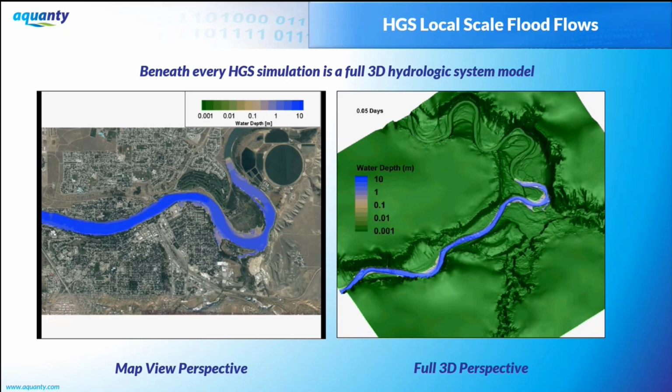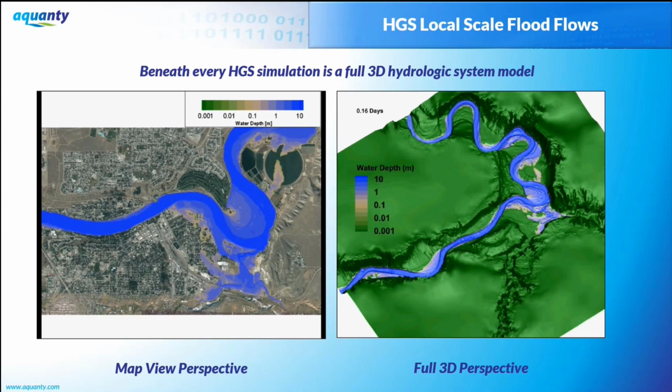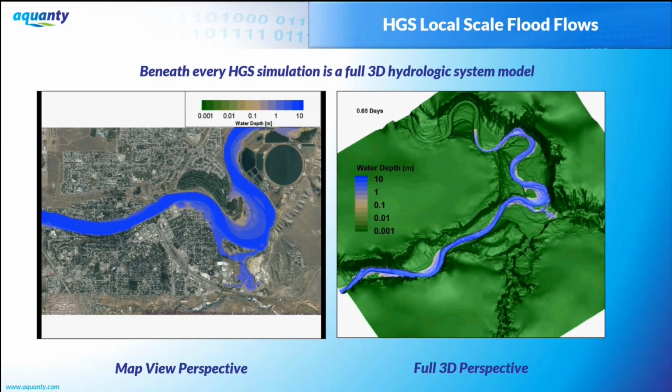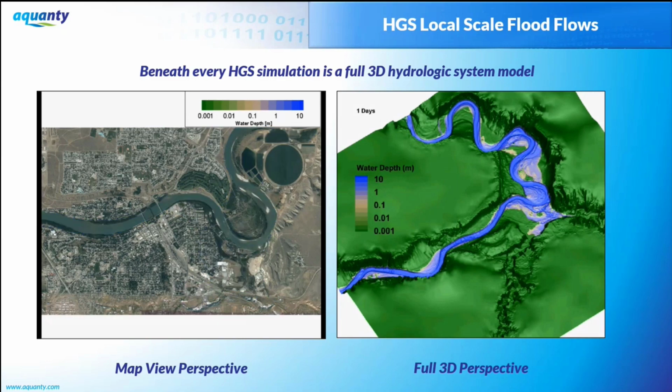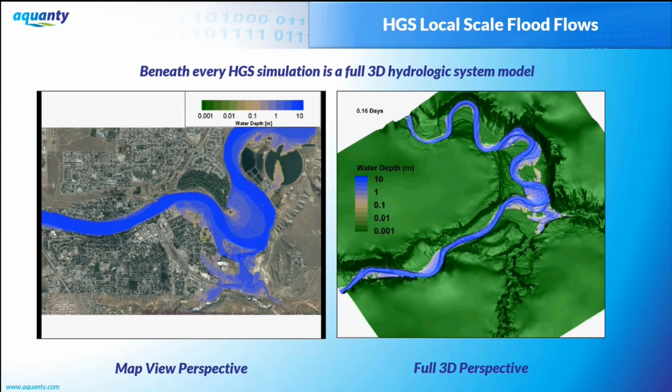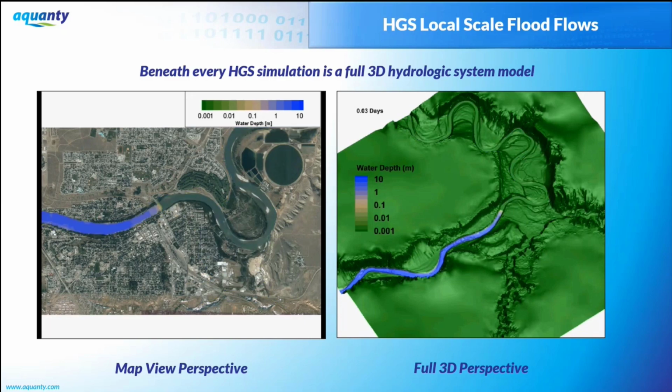It actually agreed extremely well with what was mapped during the flooding event. Now, what we did, we took a larger model, one of the Western Canada models. We took the stream flow from the larger scale model and then input that stream flow to the left-hand side of the input stream and created a much, much higher resolution model. So this is an example of telescoping to gain resolution. Next slide.